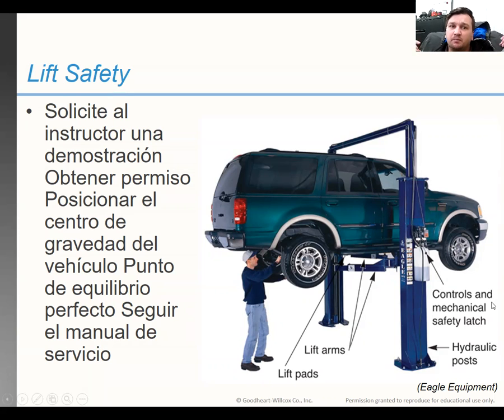It doesn't have to be completely exactly perfect, but the more you get used to it, the more you kind of figure out about where the center of the vehicle is. You want it balanced very well. If it's too far back, you run the risk of the vehicle flipping off backwards. If it's too far forward, it could flip off forward. So the center of gravity is obviously the point of perfect balance. Sometimes you can follow the service manual. It will have where that might be and everything.